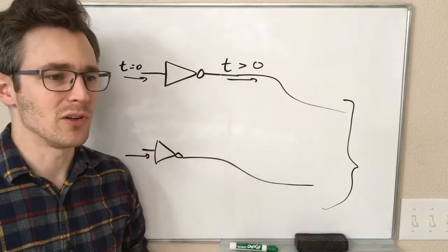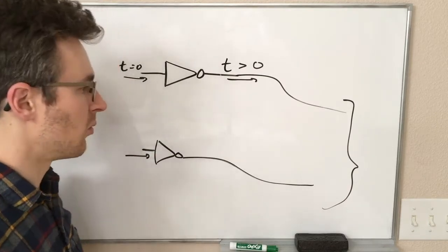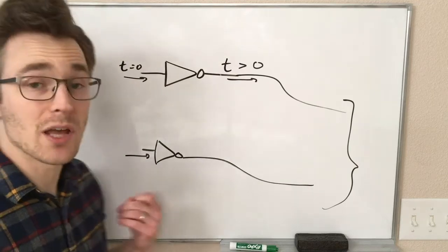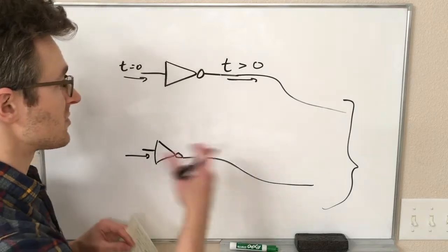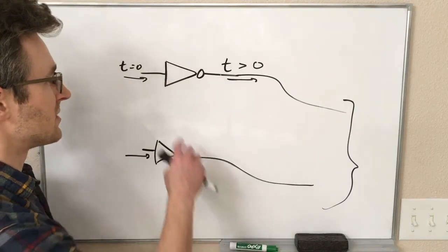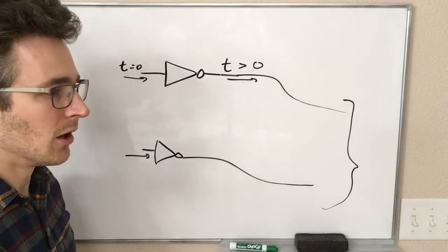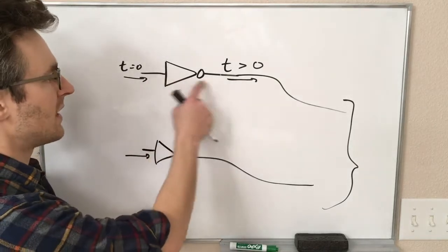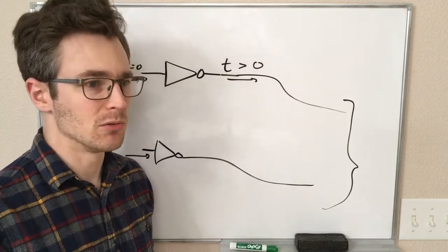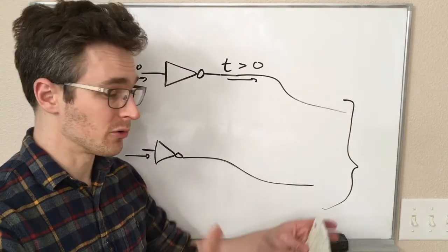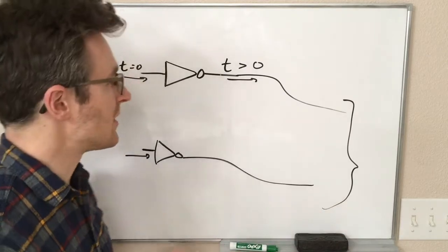Electrical signals travel a little slower than the speed of light through typical wires. And the speed of light is roughly 1 foot per nanosecond. So this also leads to one other thing. If we're talking about a delay of a nanosecond from this gate, that's also similar to the timing difference you expect for a signal to travel through 1 foot of wire, or even a little less.